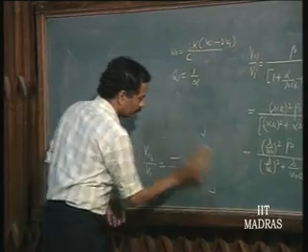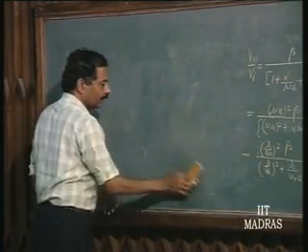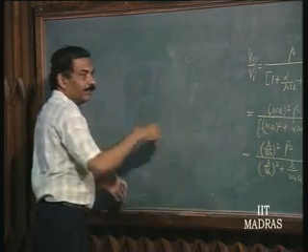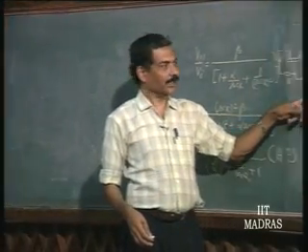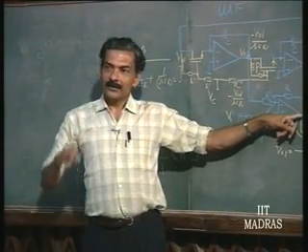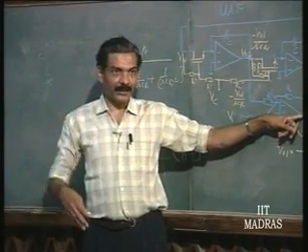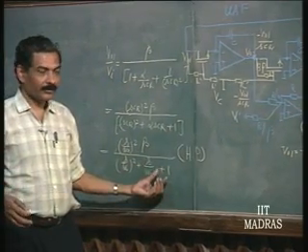Now, this linear voltage controlled filter can be tuned based on this control voltage. For example, let us take the same example. If it is some specific frequency you want to get rid of, you can make Q fairly high, let us say 100 or so.